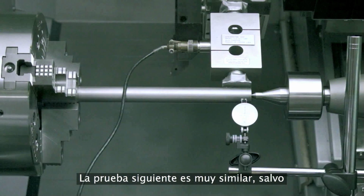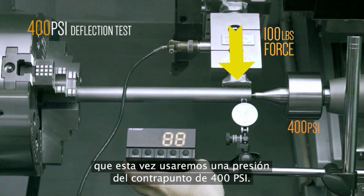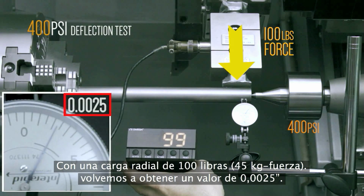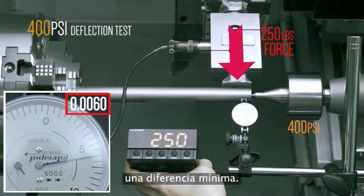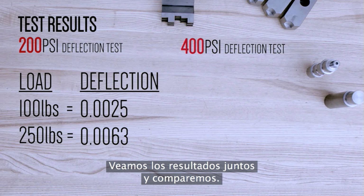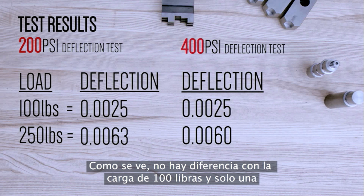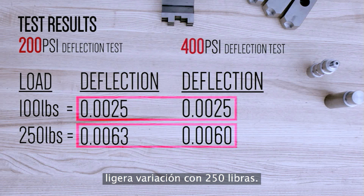For the next test, everything's the same, except this time we're going to use a tailstock force of 400 psi. At the 100 pound radial load, we get 2 thou 5 tenths again. And at the 250 pound radial load, we get 6 thou, which is only a few tenths different. Let's take a look at these results side by side and compare. As you can see, there's no difference for the 100 pound load and just a slight difference at 250 pounds.